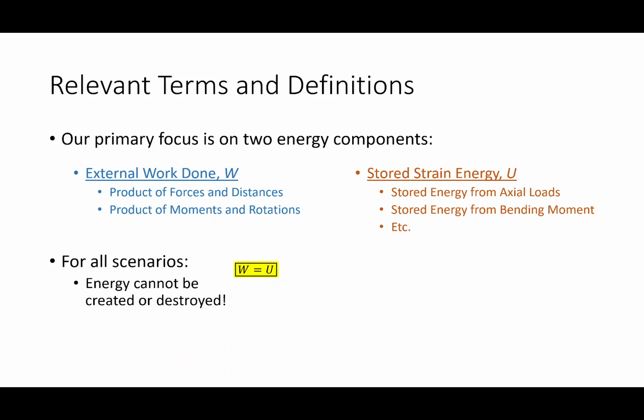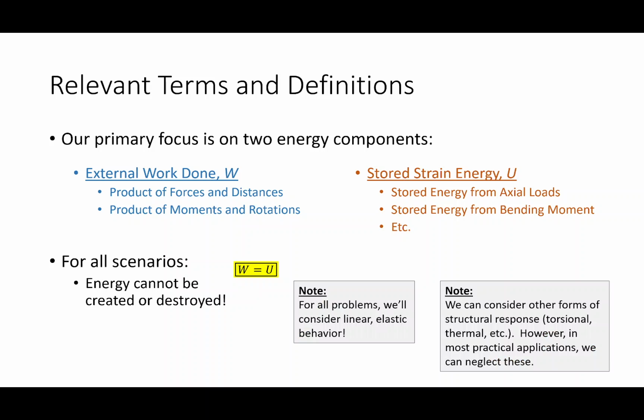Now, there's a couple of assumptions that I'm making here. For example, one of the assumptions is that there is no vibration. If I wanted to include kinetic energy, I can look at vibrating structures, and you would kind of need to do that if you were looking at earthquakes, for example. You would have to account for the fact that as an earthquake hits, the building moves. So there's a kinetic effect as well, so you've got to throw another term in there. The math gets a little trickier whenever you have vibration thrown into the mix, but we don't have to worry about that in here.